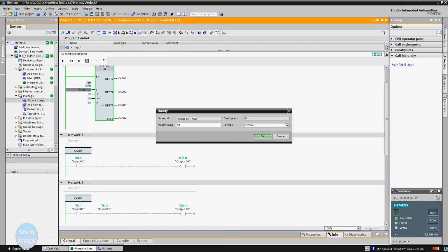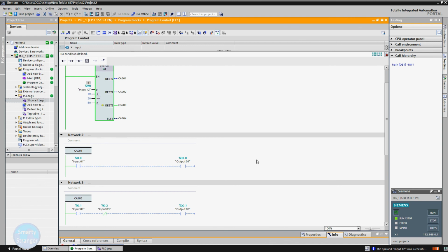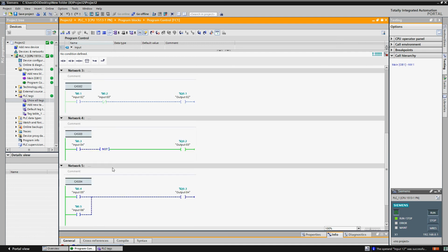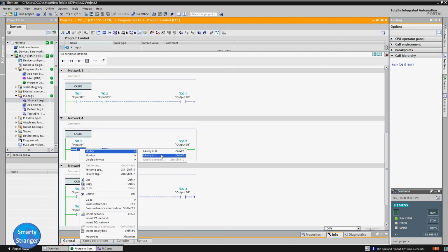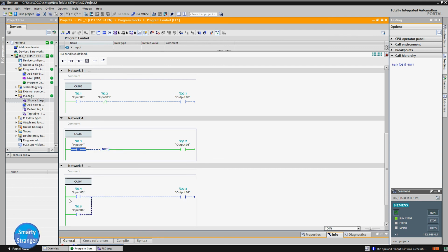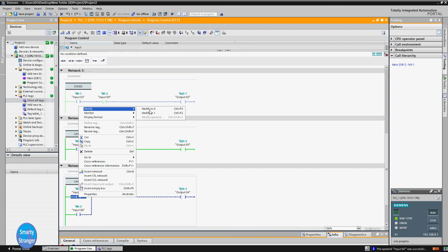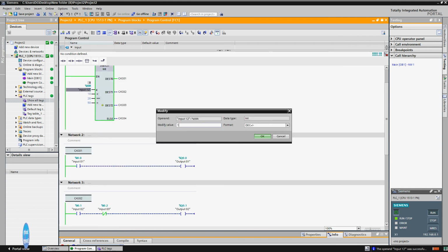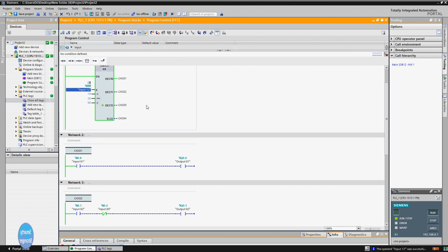Check when we apply 51 at K input. The third comparison test passed. 51 is greater than 50. So, network 02 and 03 are bypassed. Here you are seeing that network 04 and 05 are in operative condition, but network 02 and 03 are not. When we apply 100 at K input, label CAS03 is activated. Network 02 and 03 are bypassed.